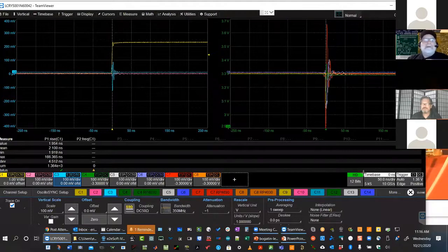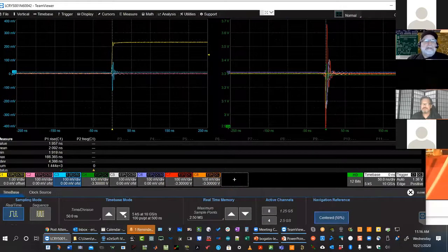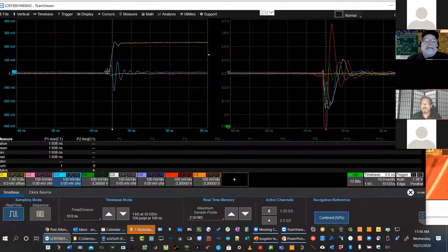I'm going to zoom out a little bit so we can see that a little bit better. And here we see a tiny bit of noise on the board, a lot of noise in the package. This is ground bounce because of the package leads. Now, this is the case for really good layout. Best you can do. Nice return plane.